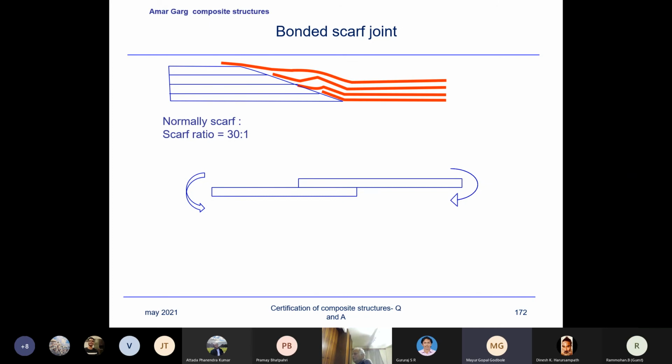Well, usually it will be a part of the process. Process specifications will be provided to the airline. So this will be part of process specifications in the repair manual, what is to be done. But you quantify the quality of the machined surface, like how? Well, usually it will say, okay, 150 grit sandpaper, you sand it to smoothing, or like that. And that's it, usually. Okay. Thank you.